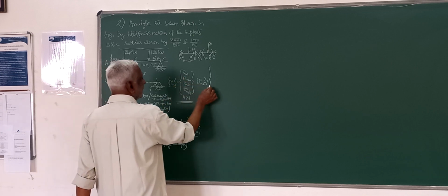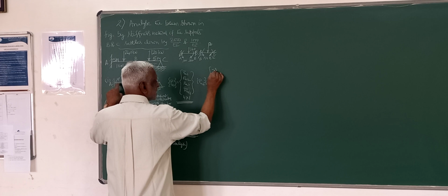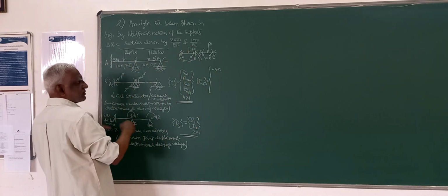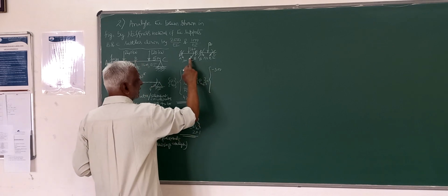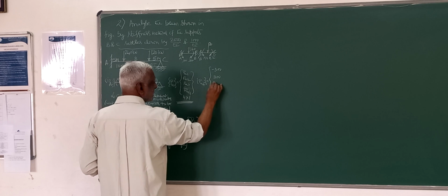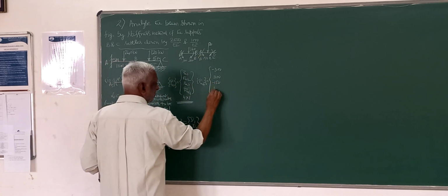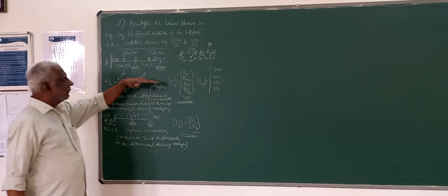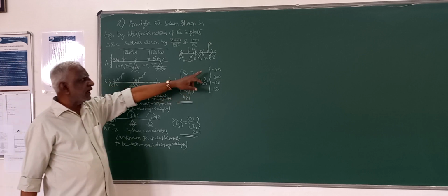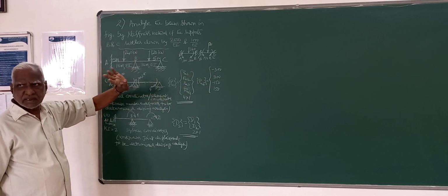So that is PMF 1, it is 300, in the anti-clockwise direction. It is opposite to this direction, so it is minus 300. Here it is 300, then here it is 150 for PM3, and PM4 is plus 150. Due to the given external loading, these are the fixed end actions that we have to take. That you can formulate here itself.